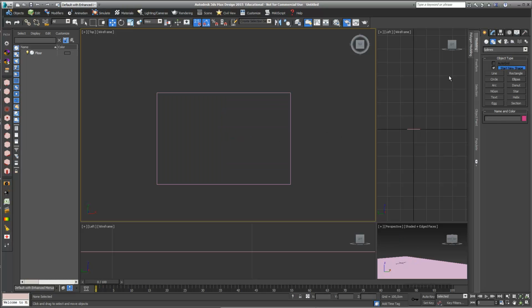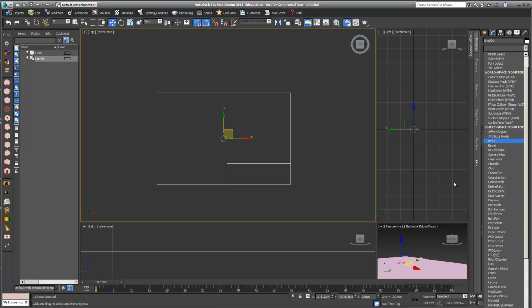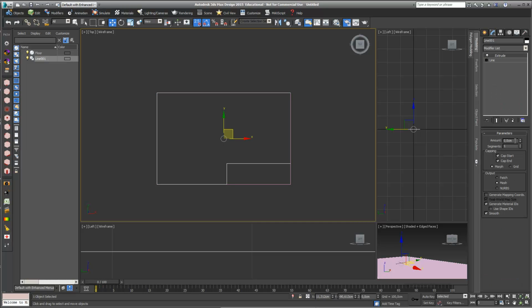And I can also just say, I just delete my line again, and I just go inside again, and I hold my shift key and I give the whole space a little bit of an edge like this, and snap here this next point, and just say this is my outline for my next steps. If I want to make a wall out of this, I can do the following, and just go into extrude and just extrude this for probably an amount of 3 meters, 300 centimeters.